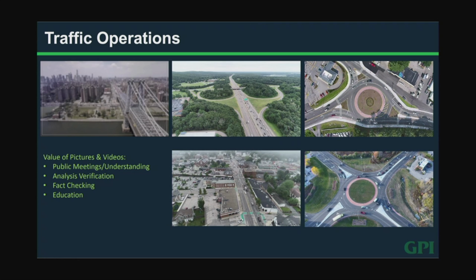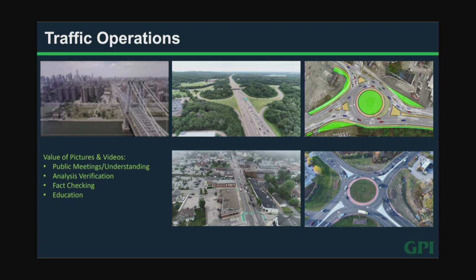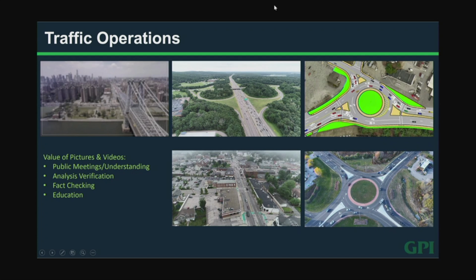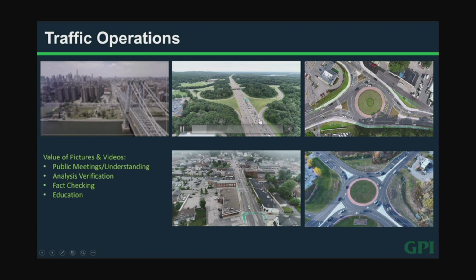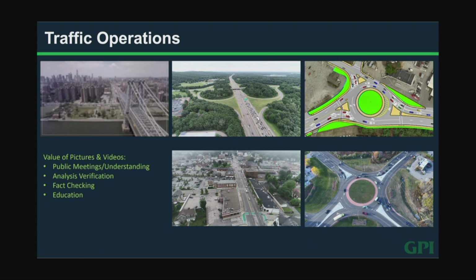We were tasked with redesigning an interchange, and we were trying to figure out, again, we made traffic projections using traffic software to see how the ramps would work. And we were looking at closing the other ramps there because of the weave on the main line there. And there was a concern that our model wasn't really accurately going to depict the potential queues that would back up along this approach. So as a start, we had modeled the existing conditions, and we went out and videoed it for about an hour to see how those related to the model and kind of calibrate that model.